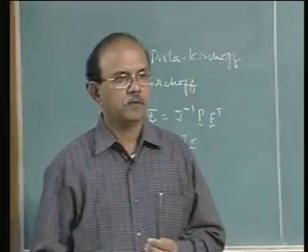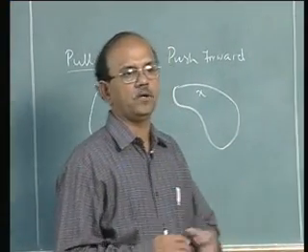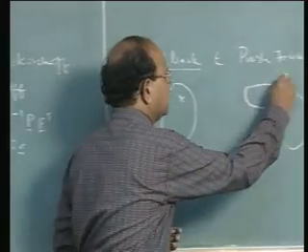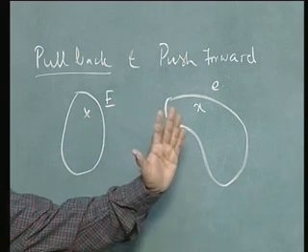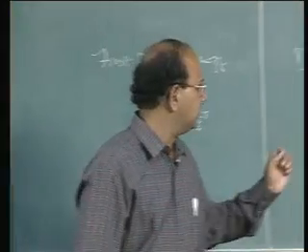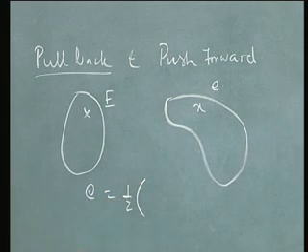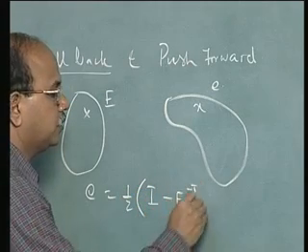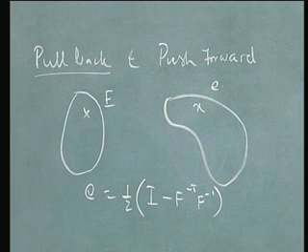If you remember, we had two quantities, and we call these the material and spatial descriptions. For example, if you look at strain, we had a quantity capital E here, defined with respect to the reference configuration, and small e defined with respect to the deformed configuration. Now, let us look at the relationship between the two, the small e and capital E. What is small e? If you remember, half into I minus F inverse transpose F inverse, which we had seen. It's very good, so all of you are familiar now with the quantities.